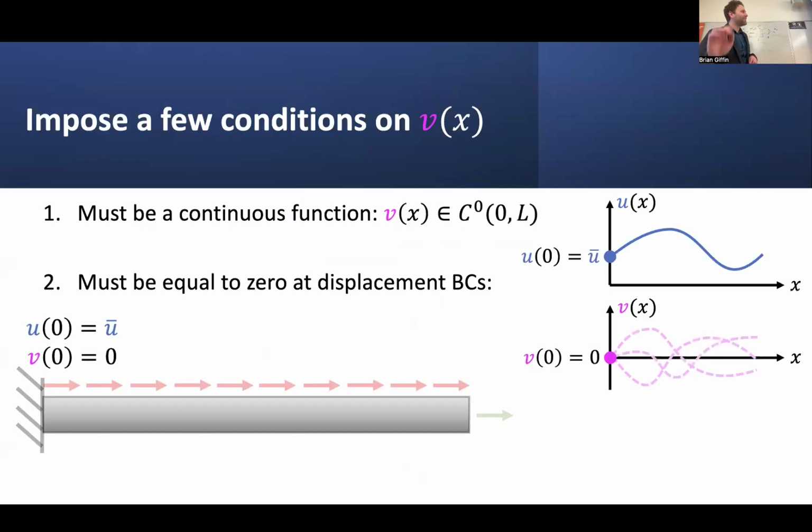All right, now that we have this, we actually have to impose a few restrictions on the way that we're selecting this arbitrarily specified test function. Now, it'll become clear exactly why we're enforcing these constraints, but suffice it to say, let's imagine that we chose this test function, and let's impose some constraints that say that this test function has to be itself a continuous function, similar in some respects to the way that we've imposed this same requirement on the displacement field.